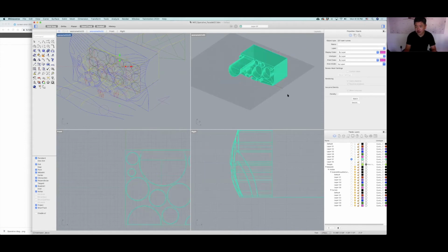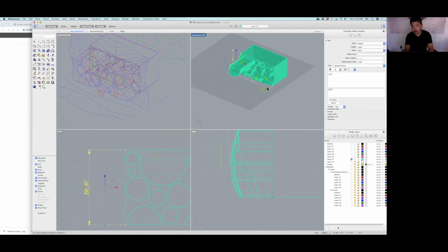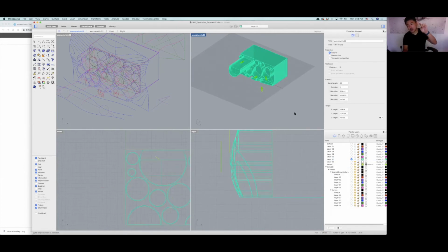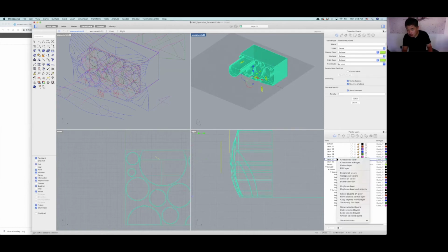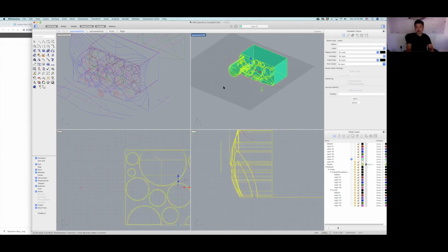Next up, it's the last one. And did I not have the swimming people? Okay, yeah, swimming people here. I would like to put all of these into my layer 7. It gets super confusing when you don't have them in the same layer. And for some reason, they are not in the right layer. So these people should be in layer 7, move objects to layer. Okay. So everything is here. Make 2D.